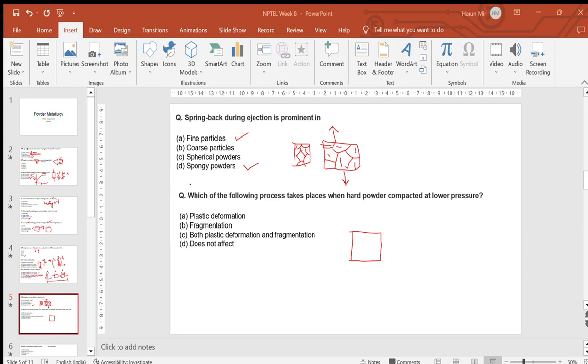But the connectivity of your soft powders is not a significant parameter when you're trying to talk about a mixture of hard and soft materials, because soft materials have an inherent tendency to undergo ductile or plastic transformations. So the connectivity of the soft powder is not much of a factor here, but the concentration of the hard powders is an important factor.